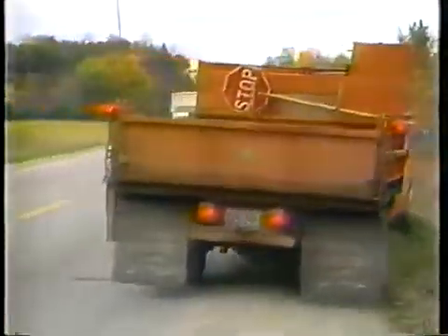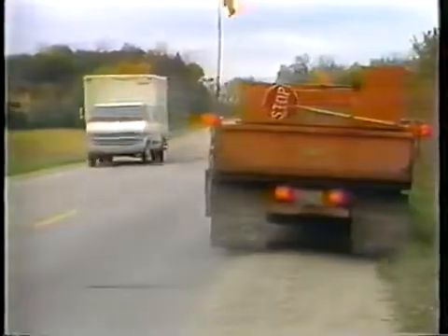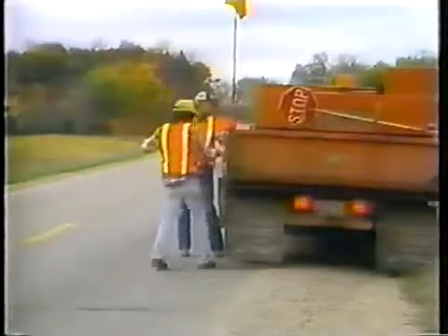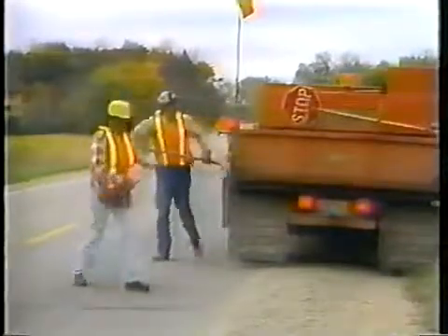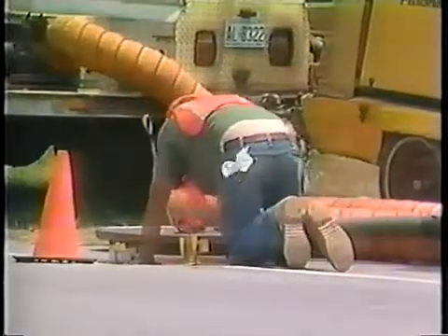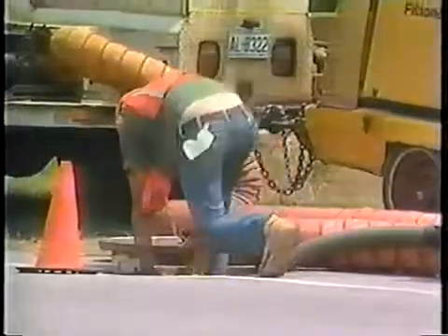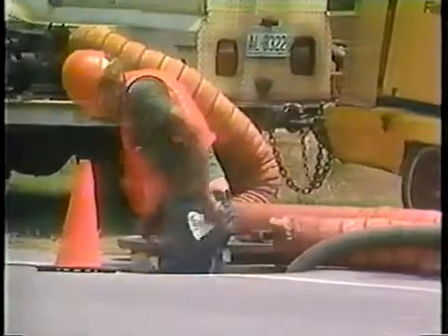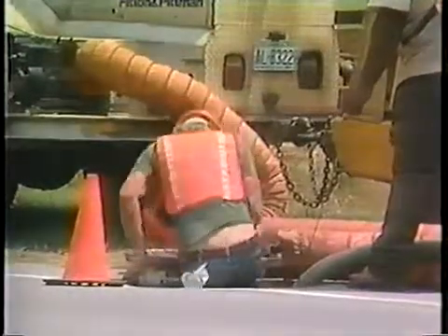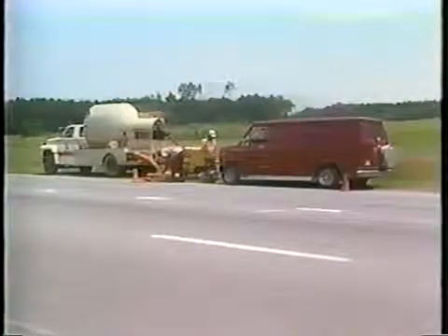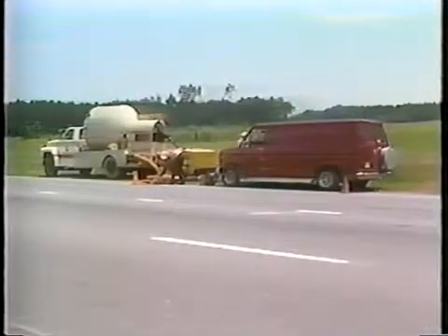Despite the brevity of short-term operations, certain traffic controls are necessary. In urban areas, the work vehicle may be used for warning if it's equipped with flashing lights, rotating beacons, or flags. When it's necessary to enter or leave a manhole, workers should always station a work vehicle upstream from the manhole. Materials or equipment should be stored away from the manhole opening. These principles presented apply to utility work zones and are just as mandatory as those in roadway work.